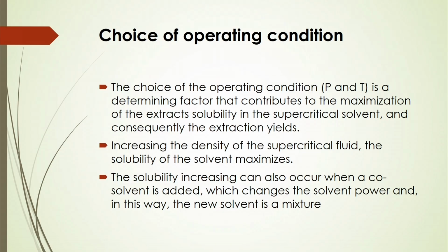Now, the choice of operating conditions: how will you choose the operating conditions for a particular extraction process? In this case the choice of operating conditions is mainly a factor that contributes to the maximization of the extract solubility in the supercritical solvent, and consequently the extraction yields.